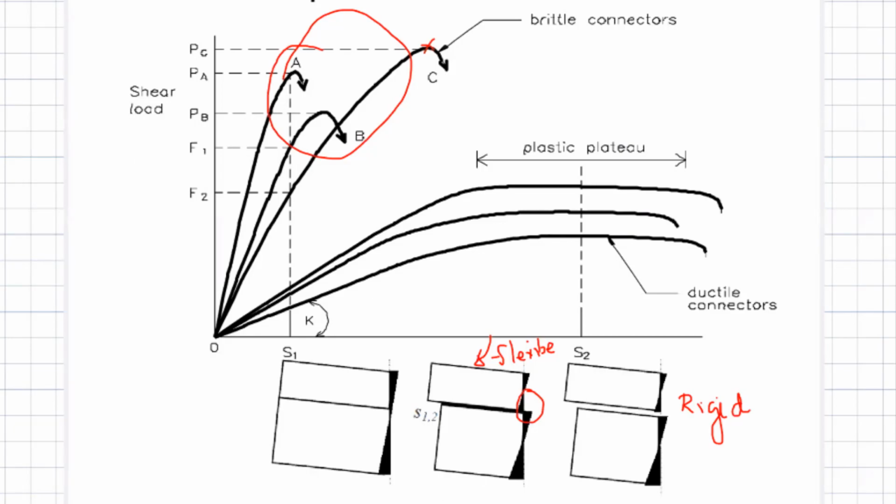So that is the reason that we say in most of our applications, ductile shear connectors are always preferred, because they not only give me the required shear strength, but also the flexibility. Now, if I can design a beam in which the shear rigidity is very high and absolutely there is no slip, you can see the bending.